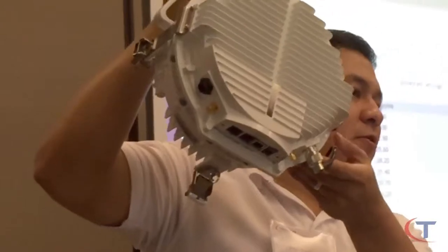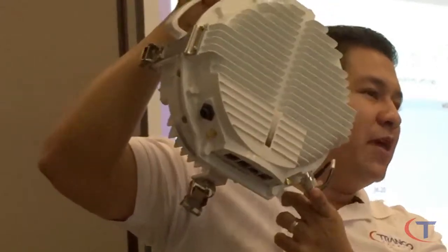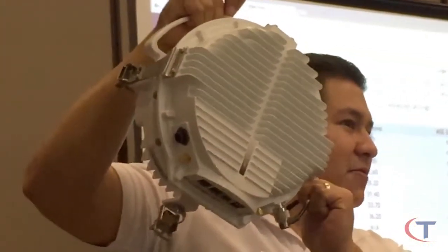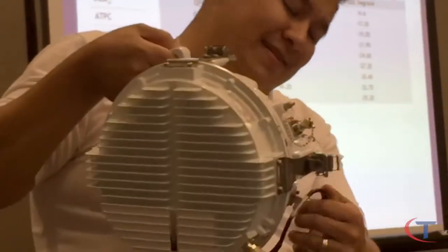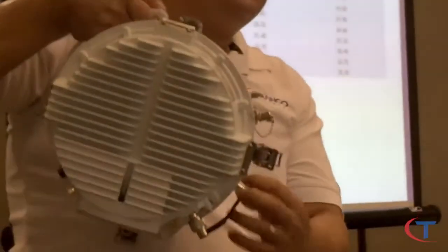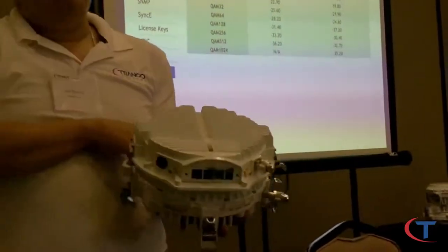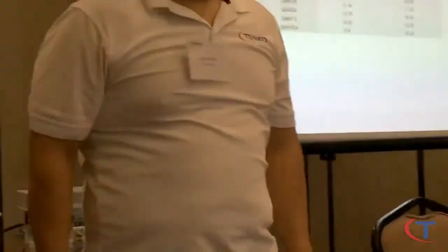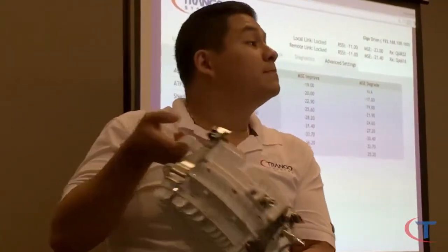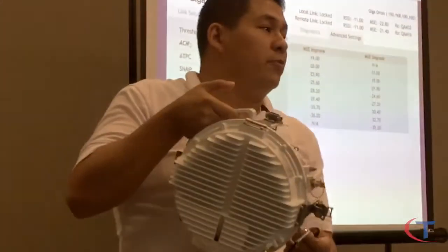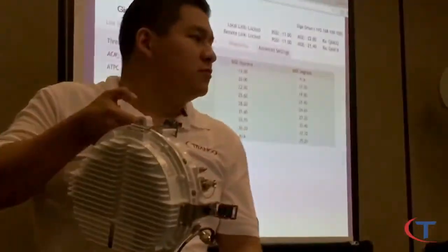This is IF frequency coming through here. So instead of that big LMR, it's just a short jumper, but this can easily get damaged as well if you use it as a grabbing handle. So thanks for that. You should be able to grab it by this. On the all-outdoor products this rarely happens, but it has to be really taken care of. It can be damaged when pulling it up the tower on a cable, and it can get nicked and banged around. It's something to be pretty cautious about. This is going to be weatherproof as well, right? You have to weatherproof those too. This already comes weatherproof. This is just my demo gear. Oh, okay. So this comes with shrink wrap on it, so it's weatherproof, so there's no problem with that.